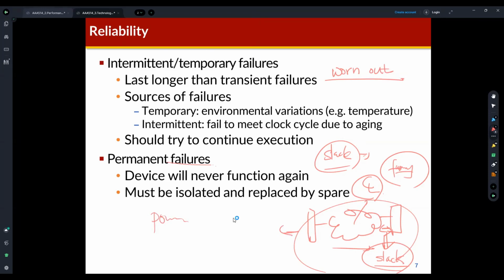It is also true for memory devices, for example, flash memory. We use flash memory as the main storage media of the SSD, but I believe some of you know that flash memory has a limited erase count. If we erase the same CMOS flash memory cells about 1,000 times, then we cannot use this cell because the cell is worn out. Okay, it's a similar issue. It's a reliability issue.